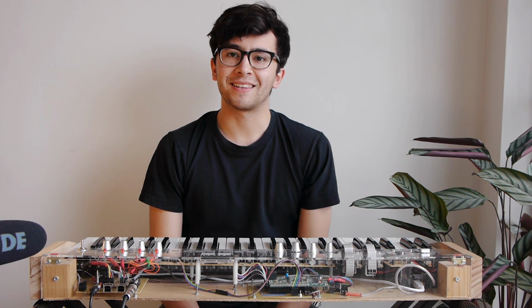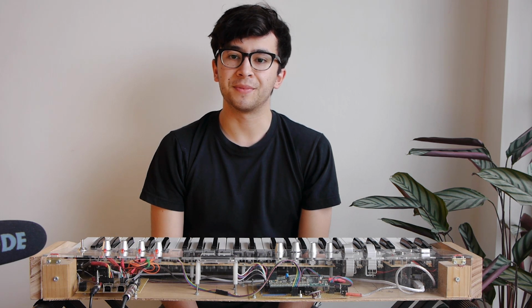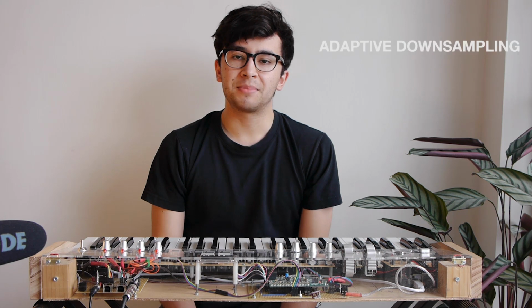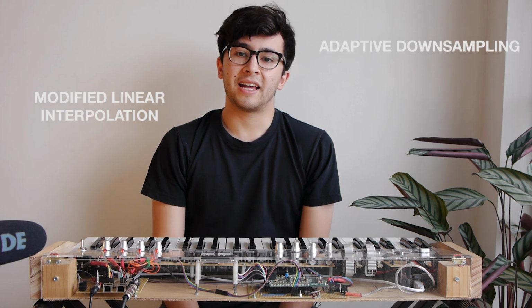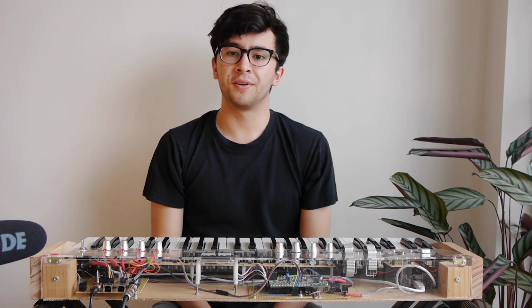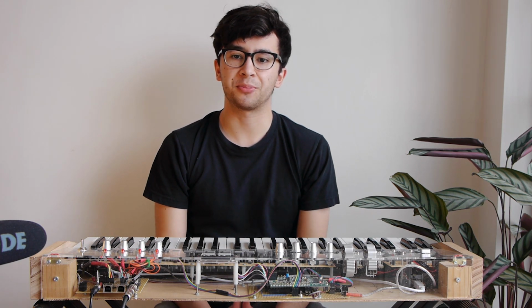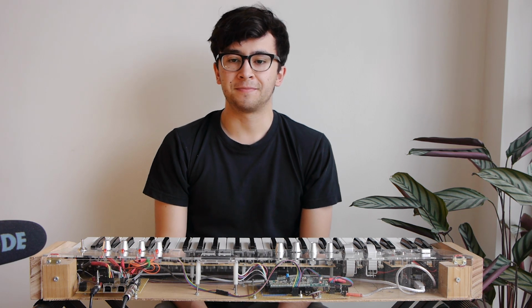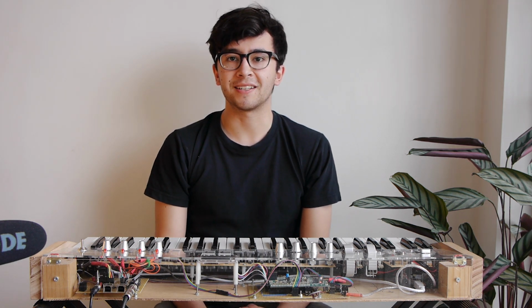While developing the synth, I've added to previous models with optimizations to increase performance and allow the models to run in real time. These include adaptive downsampling, a modified linear interpolation method, and the use of lookup tables to perform faster mathematical functions. Furthermore, I have designed and created an enclosure and supporting circuitry to be able to play the keyboard. It only requires a speaker and power. A screen has also been integrated to display the current patch and model settings.